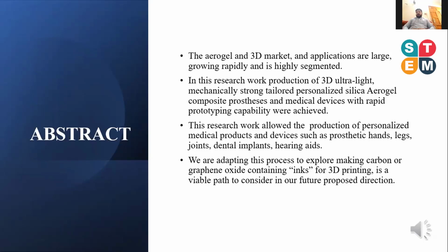which are highly porous. So, the short abstract in a few points: we know that the aerogel and 3D market and its applications are large, growing rapidly, and highly segmented. In this research work, the production of 3D ultra-light, mechanically strong, tailored, personalized silica aerogel composite prosthesis and medical devices with rapid prototyping capability were achieved. This research work allowed the production of personalized medical products, and we were able to print out the prosthetic leg, the ear, the human mandible, etc.